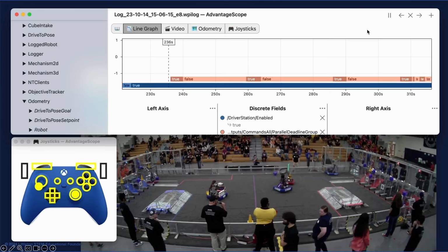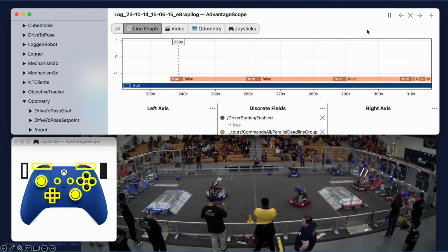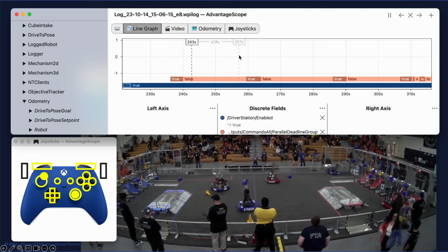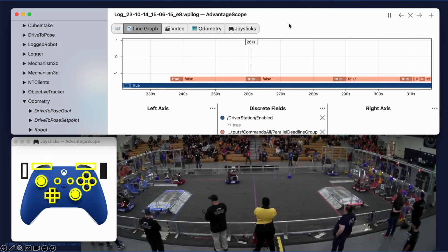For context, our 2023 robot Banana Split could score anywhere automatically on the grid using its AprilTag localization data. This video is from an off-season event and will show a few examples of this system. The state of the auto-scoring system is shown on the graph in pink. The driver pushes the right trigger to activate it. The rainbow LEDs activate. It drives automatically to the scoring position, and then it extends its arm. Here are a couple of examples of it working correctly.